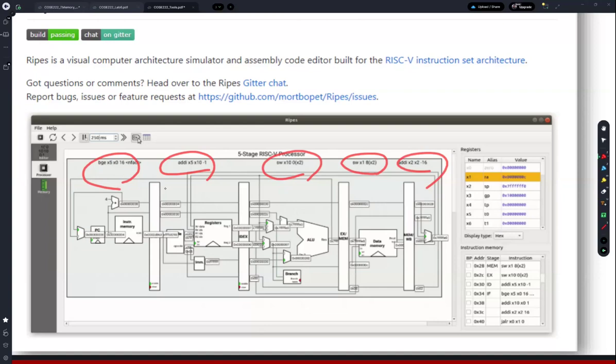We are very familiar with software coding, which is very easy and convenient. But the hardware structure is more complex, and in order to handle exceptional cases or boundary cases such as the data hazard, the control hazard, and data forwarding, we may require more complex mechanisms in the hardware.